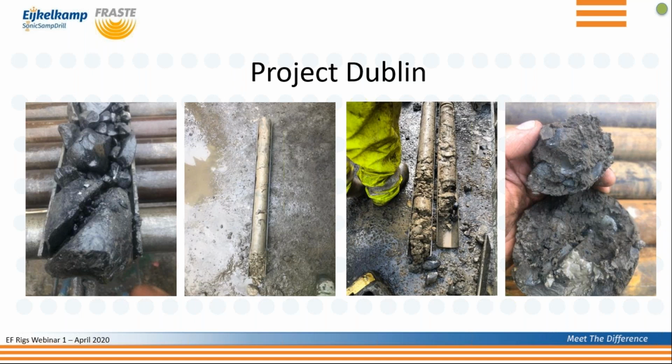So Sonic is known, well, the rumors are that it is expensive to use. But how do you experience in your jobs to use Sonic comparing to all the other methods on the price it will cost to drill it? It can be quite misleading, Sonic, in this area, because if you're on a large-scale project with multiple holes, Sonic's going to be cheaper. It's going to be cheaper than rotary. It's going to be cheaper than cable percussive, believe it or not. And people don't want to hear that, but that is the fact, and we've proven this.